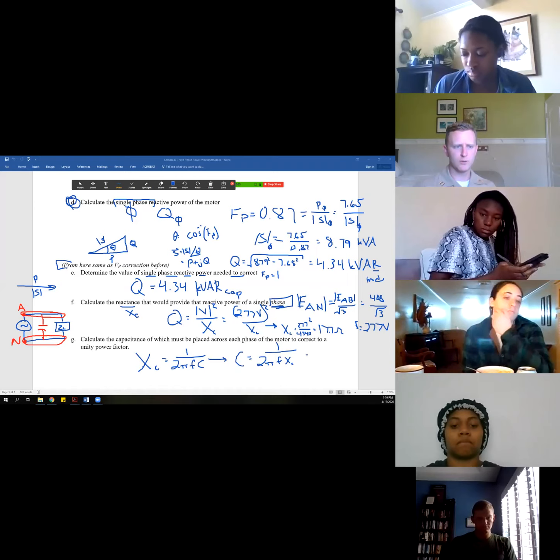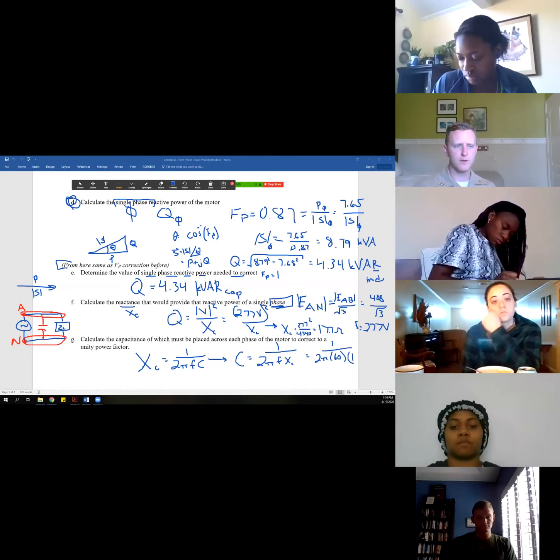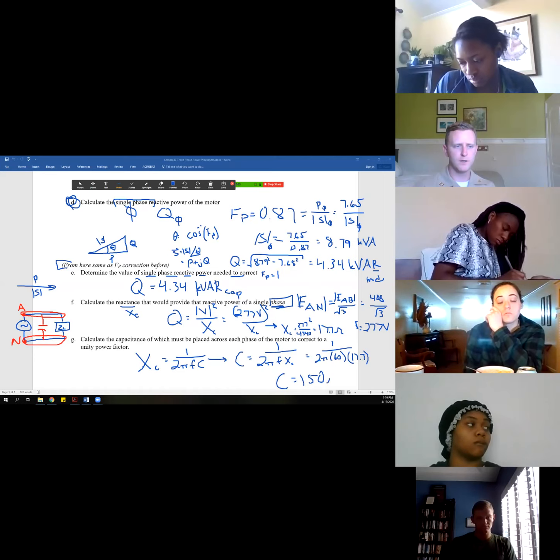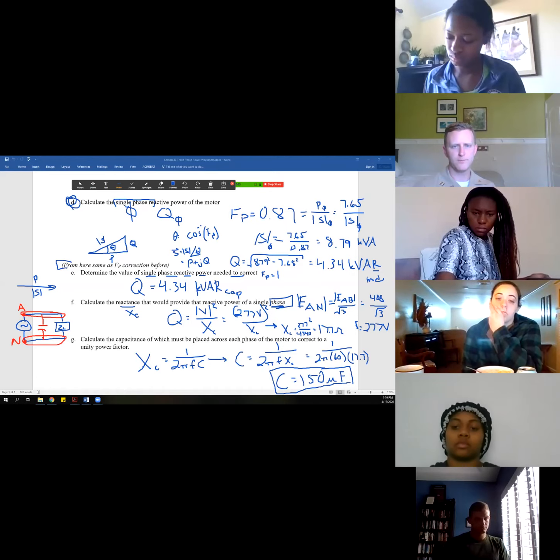Everything is pretty much on 60 hertz, all your wall outlets. So now we have 1 over 2 pi 60 times the X sub C, the 17.7, and our final capacitance comes out to 150 microfarads.